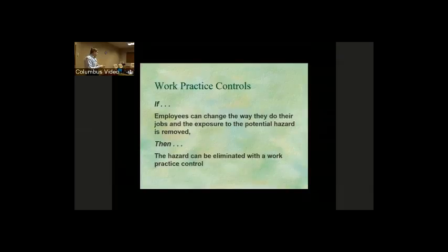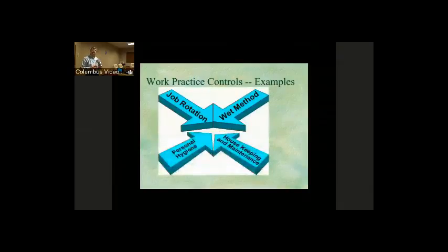Some of those can be, if you're cutting dry concrete, such as in the construction industry, instead of just cutting it with a dry saw, you can use a wet method. Again, job rotation and move employees around where we think there may be a hazard. Personal hygiene, housekeeping, maintenance. Yeah, keep the dust swept up on a regular basis. Dust on the floor, anytime somebody walks by, anytime a forklift runs by, dust gets generated into the air. So again, proper housekeeping, keep the areas around our saws and other equipment cleaned up at all times and maintained.